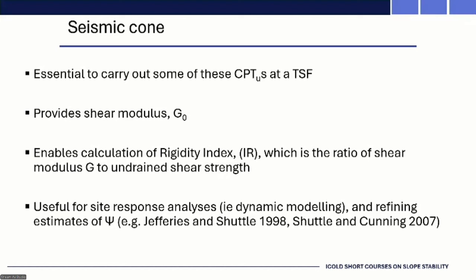Trouble is you get different numbers of shear modulus from triaxial tests, using conventional displacement measurements, using bender elements, using resonant columns, etc. So I think, again, we're still not really settled on which value of G is the one to be using. But that's used then to calculate this rigidity index. So it's important we do start to nail that down.